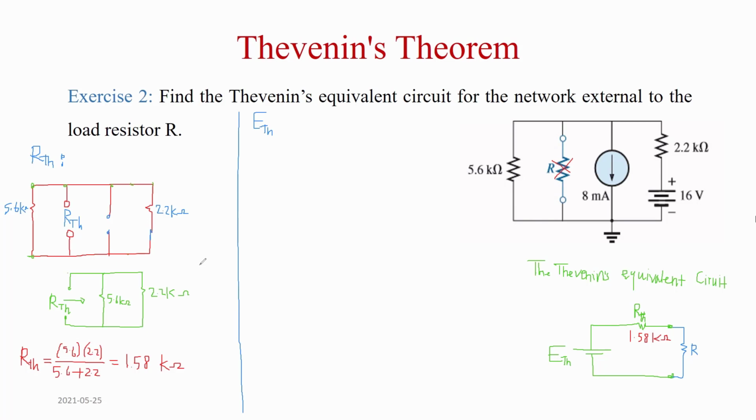If one terminal of those resistors is connected to one node, and the other terminal of all these resistors are going to another node, like here, this terminal and this terminal are going to one node. They're meeting. The other side, this terminal and this terminal of the resistors are meeting in one node, so those resistors are connected in parallel.